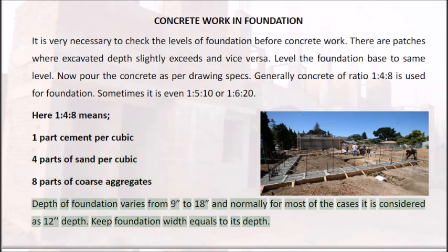Depth of foundation varies from 9 to 18 inches and normally for most of the cases it is considered as 12 inches depth. Keep foundation width equal to its depth.